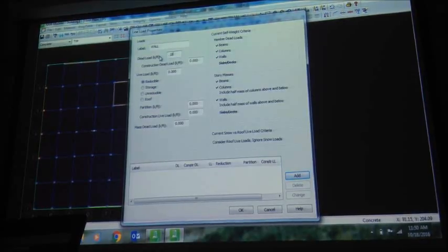Usually, if it is a 12 feet height, these walls are 15 pounds per square foot. 1 square foot is 15 pounds, multiplied by 12 feet high is 180 pounds per linear foot. 180 means 0.18 kip per foot. Okay? Depending on your building height and your wall material, you can change it. Common practice is this one.